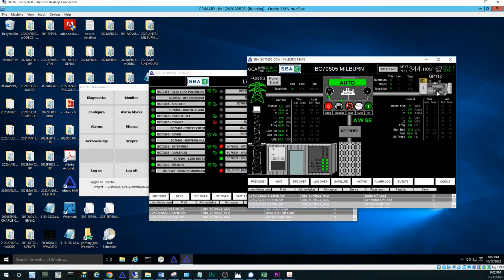Currently the generator indicator is grayed out as the generator is in the standby state. If the generator is running, the indicator will be yellow, to indicate an abnormal status, and red is reserved for operational failures or alarms. Once the generator starts and completes its warm-up cycle, the load would be connected to the generator. In this case, the load is primarily a rectifier which charges a large battery bank and supplies DC power to equipment owned and operated by multiple customers.